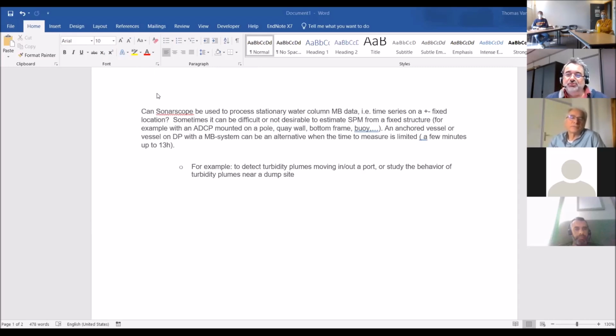So if you put your multibeam in the same place, but it must be plugged into a positioning system, a CPAS or anything, it works very well. Except that you see some vibration due to the shift of the RTK system, but it will produce data. But you need a position and a depth.